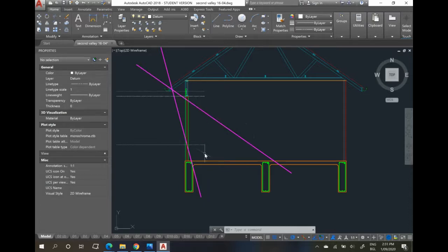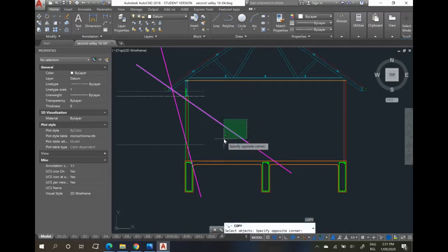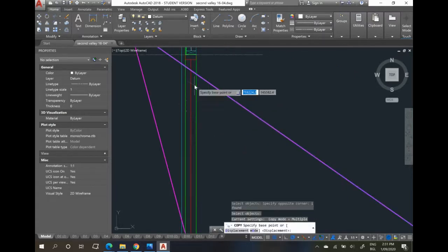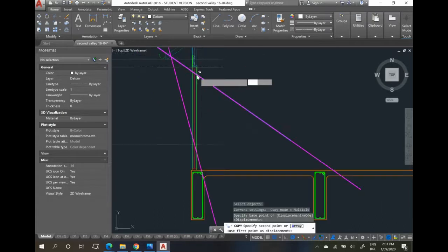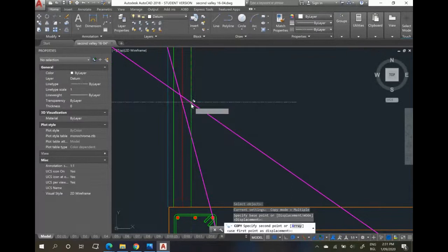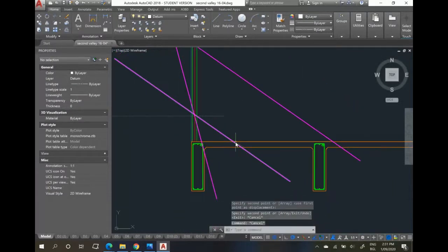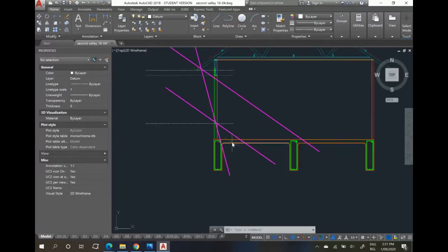You can get a little bit more tricky with this. You can get a little bit more nuanced by doing things like determining how much shading that sill will provide in winter. We can go here and get our sill for winter time and cast a shadow there, and then determine the exact amount of slab exposure to the sun there in wintertime.